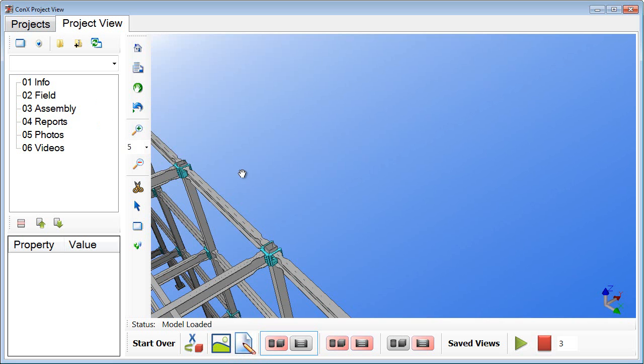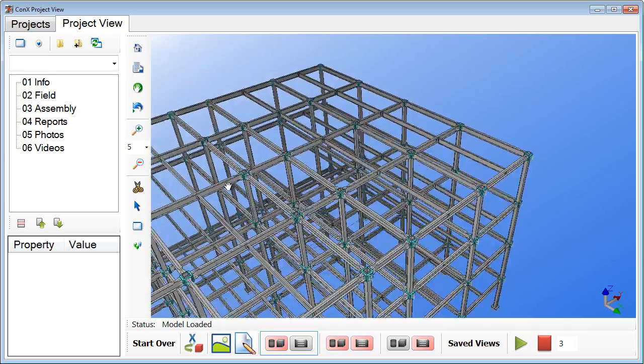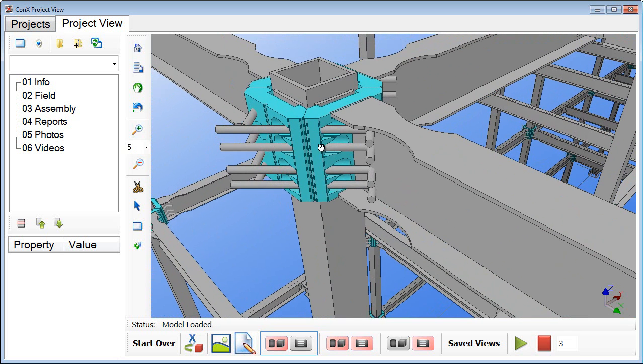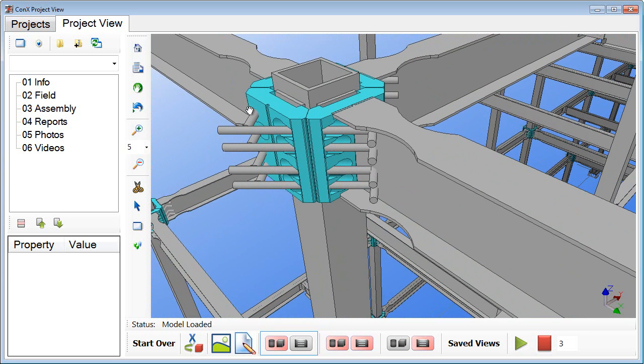And when I do that, we'll see most of the same data, except the bolts are going to look a little bit different. Notice also the tooltip data is kicking in here, right? So if I zoom in here, now you'll see the bolts, and the reason why the bolts look a little bit funky here on the node is that the publish tool basically uses the cut length property on the bolts in order to figure out what length to export here. So that's why they're a little bit long. But when I hover over each one of those parts, you'll see that that's the true length it's meant for. It's a 1-inch diameter A574 ConX node bolt by 5 inches long.